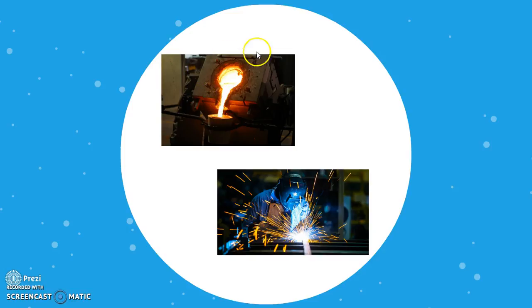So what we have here is a furnace. This tilted portion is a furnace in which we are putting the raw material which needs to be casted. After putting this raw material in this furnace, we are heating it and converting it into liquid molten metal, and this molten metal then gets collected into a ladle. So this portion in which we are taking this molten metal is known as ladle. Into the ladle this molten metal will be taken, and this ladle will be taken towards the mold into which it will be poured, and we are producing castings.